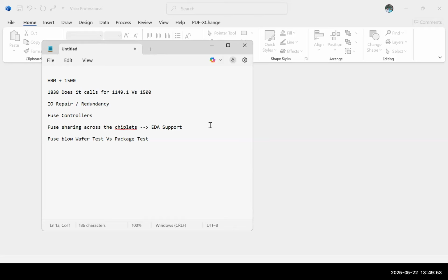I don't know if they give all this fuse related information to the firmware, like how many fuses are utilized for what access. That is again a security issue. I think the fuses can only be accessed through the TAP, and the TAP has a security key. Until you have that key, you cannot read out fuses.